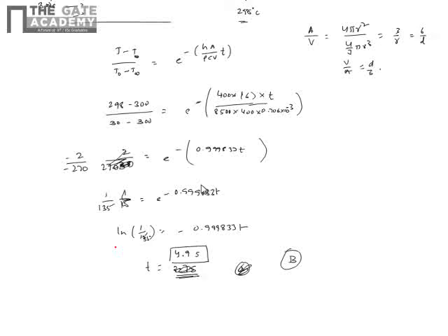So in all these lumped analysis problems, the only basic formula is this, whether it's quenching or heating. Here it was heating of the surface from 30 to 298, and we have solved one more problem which was quenching in air or quenching in an oil bath. All these kinds of problems use one and the same formula. You have to just properly use it.